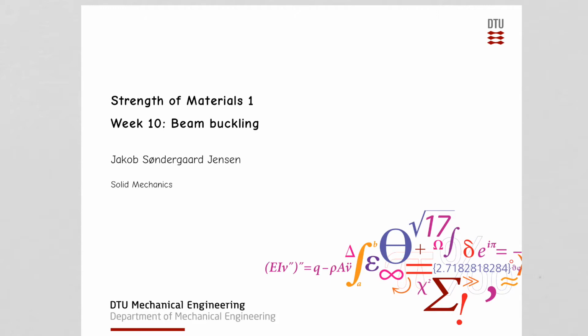Beam buckling is a really important phenomenon. We will see that when we design structures, of course, stresses in beams due to bending are very important, as we have looked at the last weeks. It can often be the deciding factor when we decide how we dimension bars and beams, the dimensions, the thickness, and so forth.